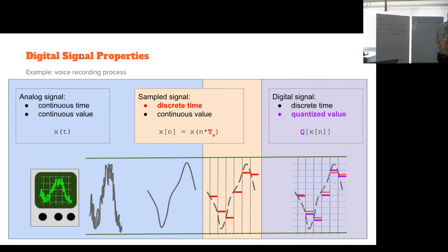And the last one here is the digital signal, which, in addition to discrete time, also has quantized value. So it's not the real value that the signal had, but the closest that you can represent with that A to D converter. Most of this course, actually all the 5 exercises we have, is more about discrete time but almost continuous value, since we are using floating point accuracy. Going to this one would be a more advanced topic, but if you are interested in this quantized signal and what it does, you should take that extra part, which is called embedded DSP.